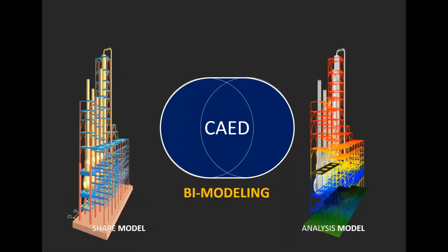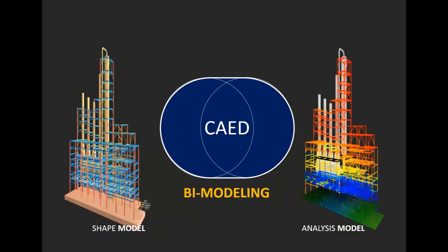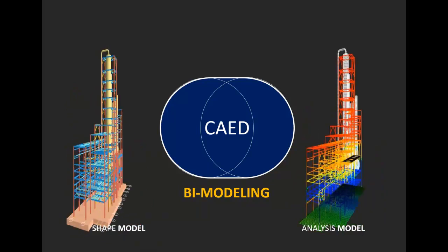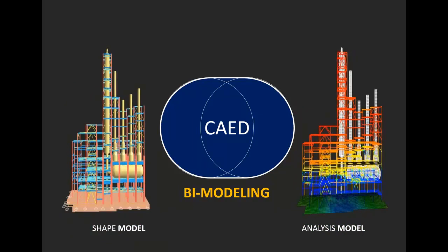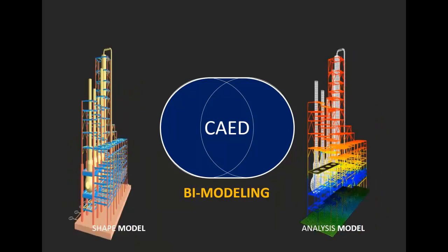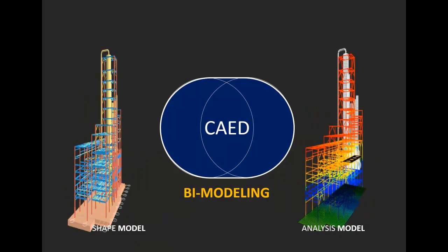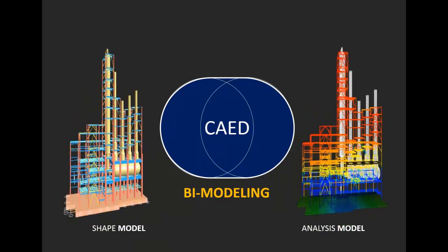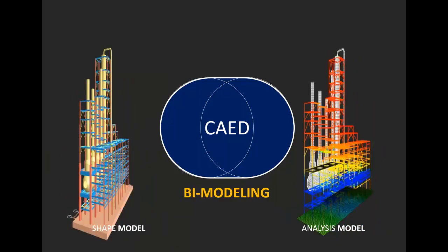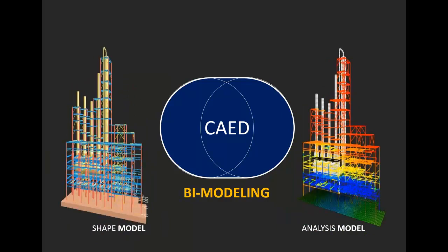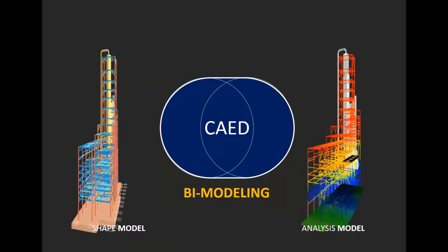Now only the geometric modeling is done, and the analytical model is created in the program. Now you don't have to think about the difficult concepts of finite element, mesh or node, which are concepts used in analytical models. You can see you're now free from the mesh.